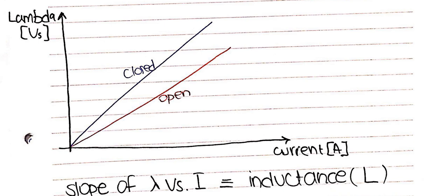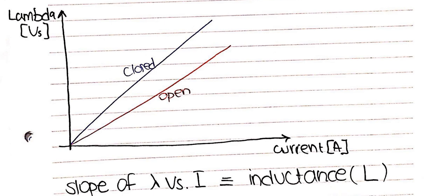Since the magnetic field produces a force, the plunger starts to move away from its initial position, closing the air gap. As the air gap is closed, the reluctance of the whole ferromagnetic core changes. It actually decreases. This means that the inductance of the circuit increases.